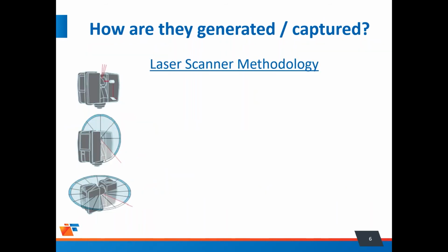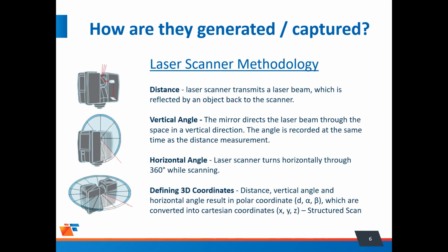So as far as moving on to the laser technology, I just wanted to touch on a few things. Laser scanners use a laser to measure the distance to the object and are extremely accurate. So the laser basically spins vertically and horizontally to capture all the points around the scanner. Once a location is captured, the laser is physically moved to another location and another scan is taken. So laser scanners and focus light scanners like the Matterport are similar in that respect.